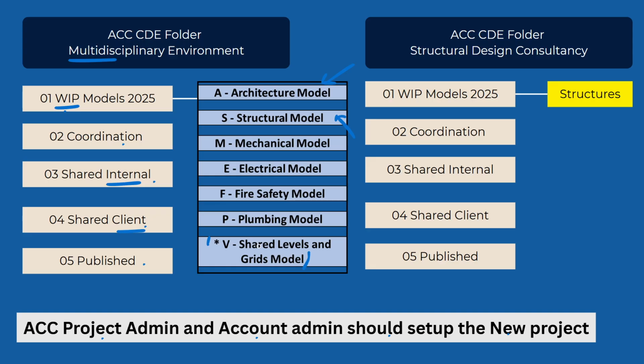Yeah, as a BIM coordinator or BIM manager, we set up that model which contains levels and grids which are shared with these models. If there are any changes to the levels or grids, you just change it here, and these models will be automatically updated. So you need to have more control over that. As a BIM coordinator or a BIM manager, when you set up any models, you should be aware of the levels, the grids. This generally we call a standards model.